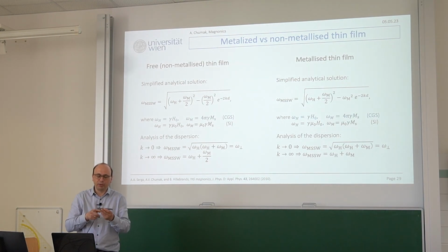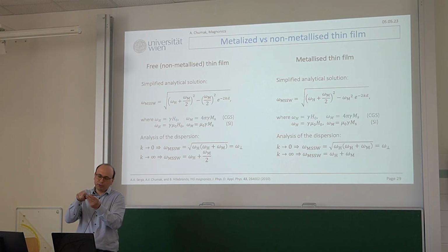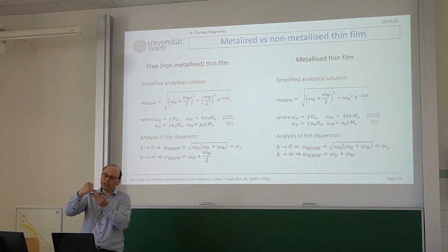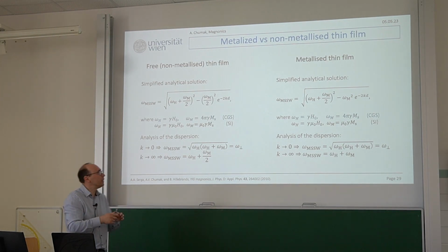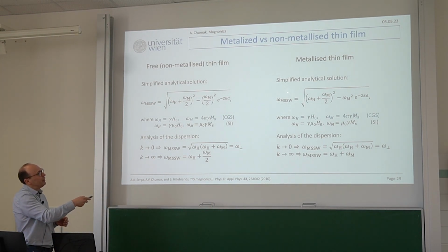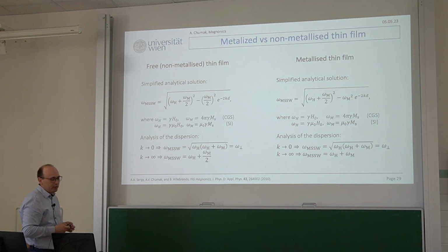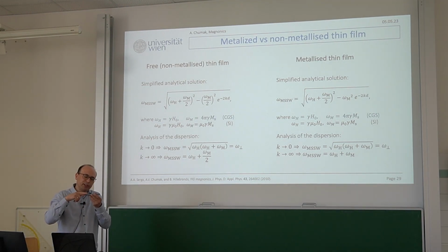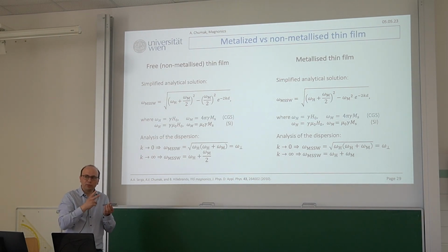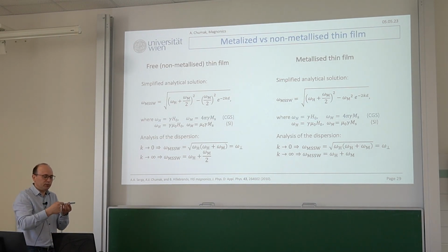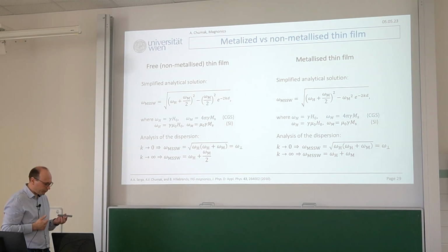you put metallization, because if you have antenna, free sample, and then metallized starting from some point, when the wave is running to this metallization point, it has to change its dispersion. Yeah? So it had one dispersion in the free path, and another dispersion for metallization. So it means for the given frequency, it should make a jump in k. And then it might make a jump in k, or it might reflect. Then you need to analyze the situation, but principally expect always reflections from metallization.